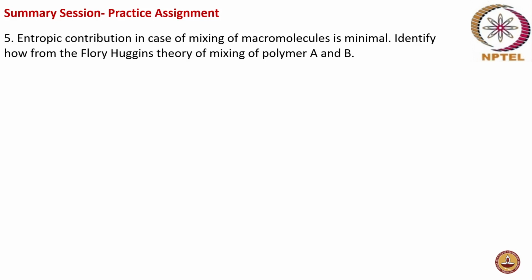For the mixing of polymers, the contribution of the entropic part is very small. So we have to find why it is small based on the Flory-Huggins theory. This is the question.